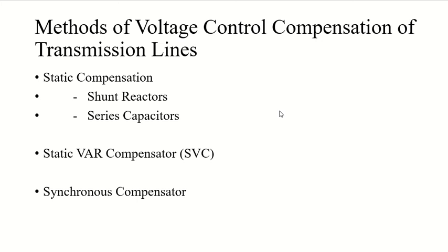It is also used for improvement of power factor, which we have shown in the previous playlist of this subject as well. And it also reduces the kVA loading of generators and the circuits, right? So basically we are just preventing the system voltage in some of the buses from becoming higher than the nominal voltage, because it can cause a lot of damage to your system, right?